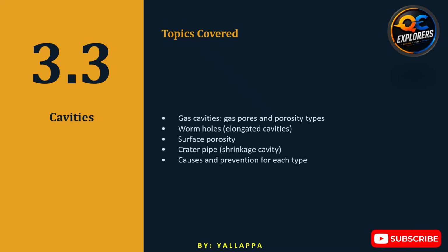As we continue, keep this distinction in mind. Gas gives rounded morphology. Solid inclusions generally give irregular morphology. We will now examine the causes and prevention of gas porosity.